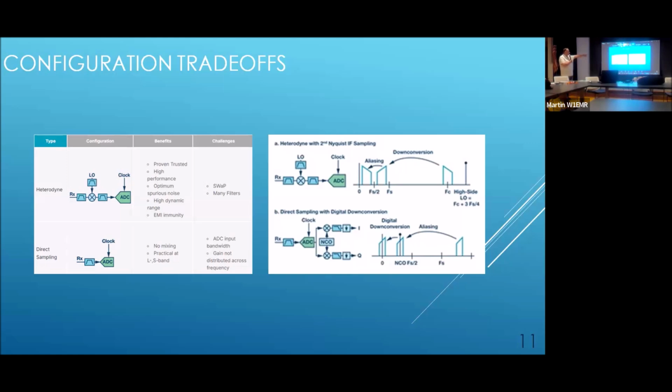And here you see some examples of what the signal outputs look like. On the top with the heterodyne effect, on the bottom with digital mode sampling. And this one has something which I'm not talking about, which is that the outputs are an I output and a Q output, which are 90 degrees in phase difference between them. I is in phase and the Q signal is quadrature phase. And this basically allows an IF stage, the numerical processing, to be a lot easier to get rid of signals. Okay, next slide, please.